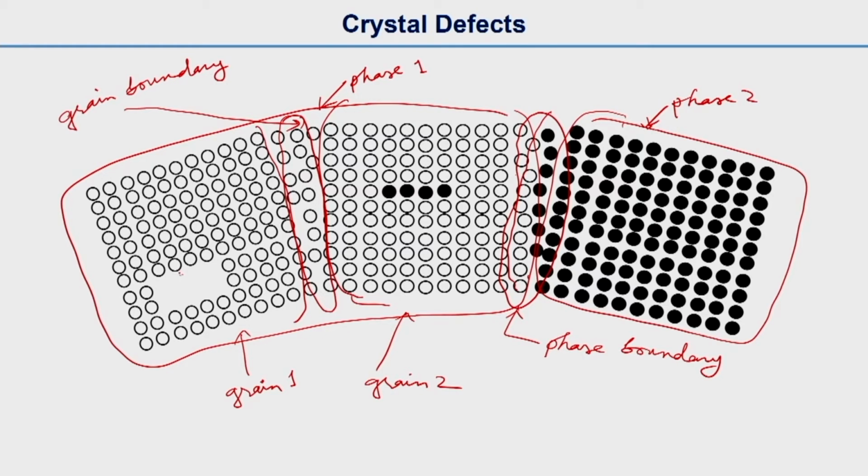The grain boundary is also a crystal defect, as we have discussed, a 2-dimensional crystal defect. Similarly we have a vacancy zone. This is a group of vacancies, or we can call it zone of vacancy. As I already told, these 3 figures, these 2 slides and the earlier slide are from Mark Meyers' book, figure number 13.7, zone of vacancy. And similarly there are some foreign atoms that group together. That we can call zone of foreign atoms.